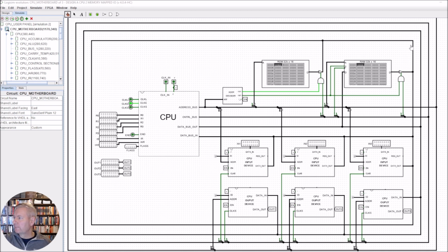And you can see this bus, if you follow it round and down, it goes back into the data bus in, so it goes into the CPU. So we're taking information out of the ROM, down and into the CPU whenever the control bus tells us to enable that information, and also whenever the address is in the addressable position for the ROM.